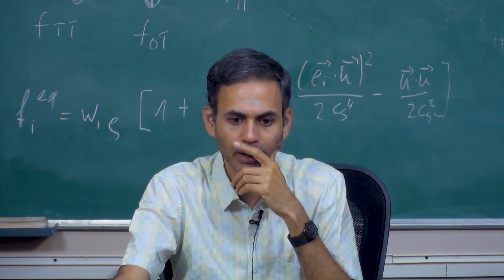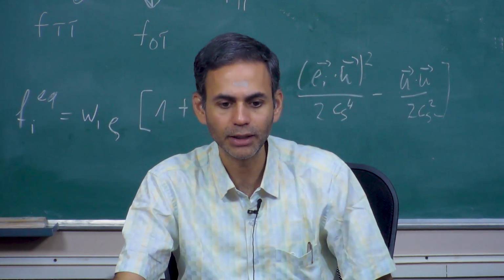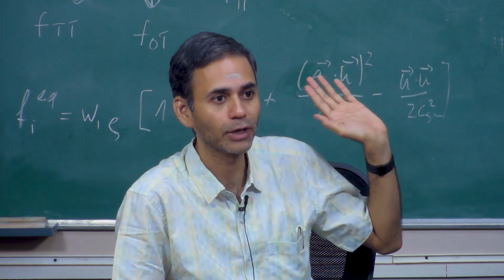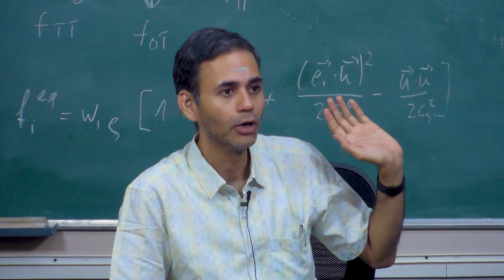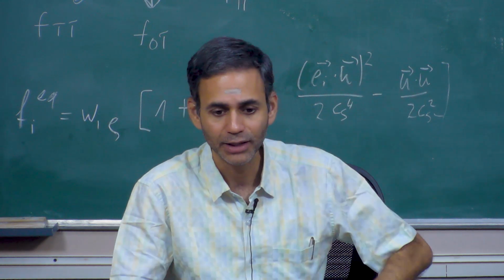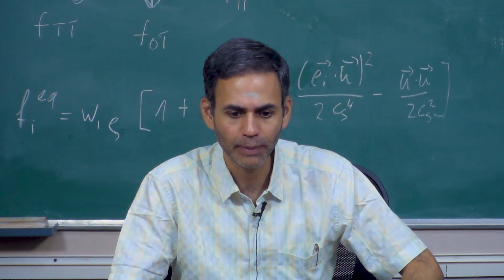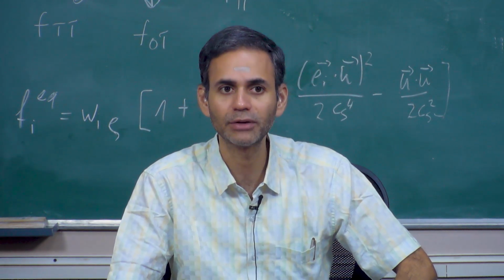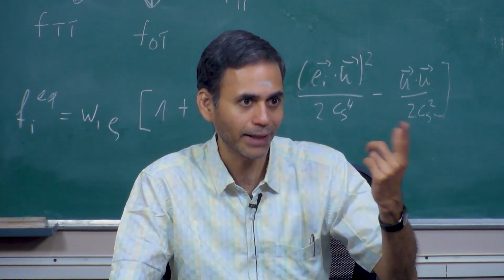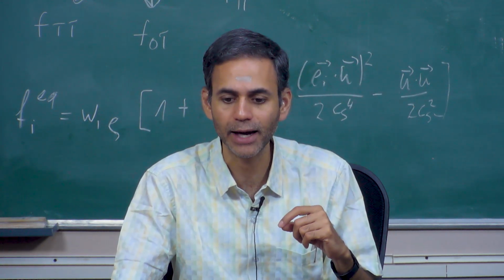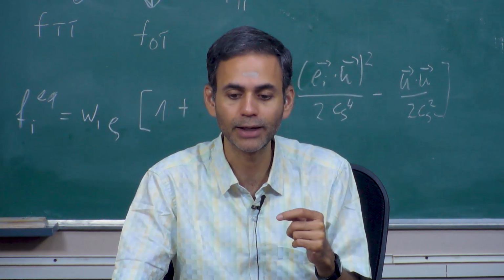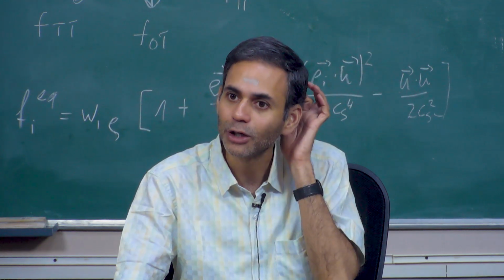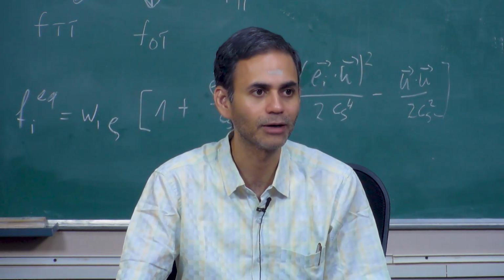As we have seen this morning, the top boundary is a velocity boundary, right? You have a non-zero velocity boundary. You have U prescribed as U BC, right? And what was the boundary condition we have seen? In addition to the bounce back, you will also have this minus 2 omega i, so minus 2 w_i rho divided by theta times e-bar dot U BC, correct? Remember, this was taught in the morning today.